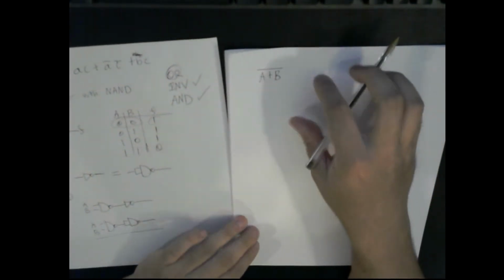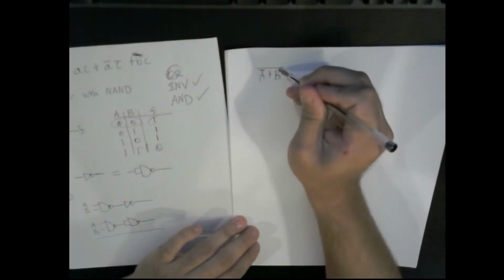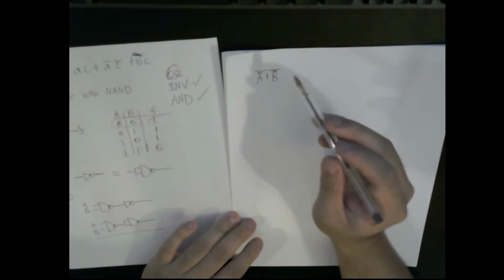So what would happen if I inverted both my inputs to my NAND gate? So I put inversions over A and B, and there's a big bar across all of them. I can do that. DeMorgan's Law is break the line, change the sign, but I can also combine the line and change the sign also. So what if I combine these two?